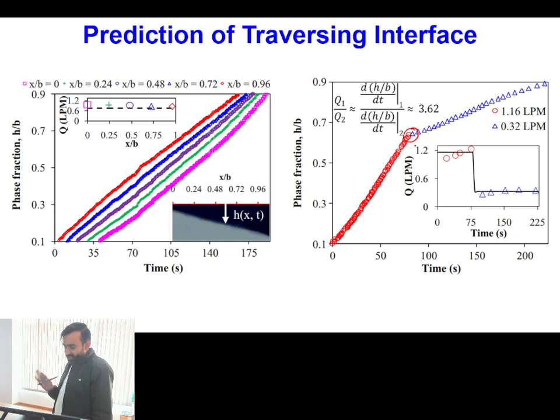Okay, so still whatever these experimental cases are shown over here for interface reconstruction and flow rate measurement, their interface movement was not very high. Okay, so the time scale of interface movement was less in comparison to the time scale at which your photodiode was responding to changes in the intensity of the light.